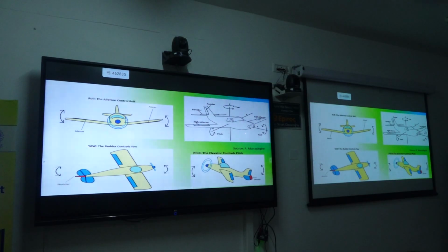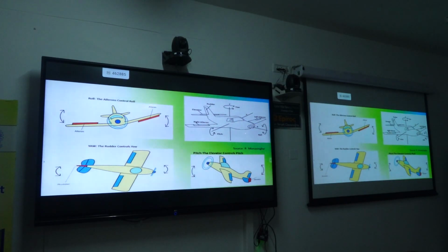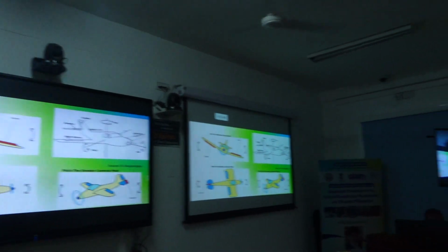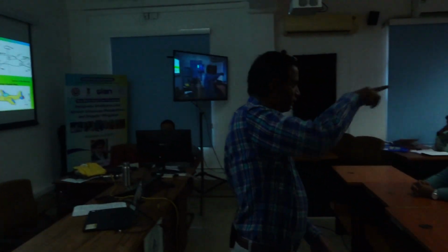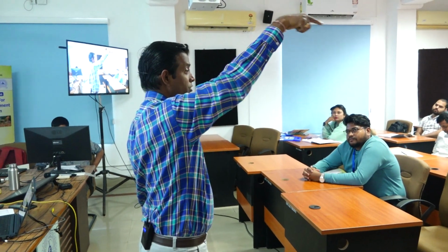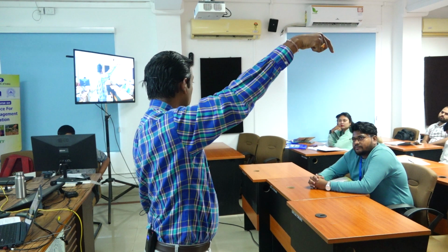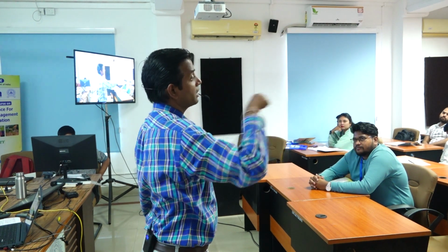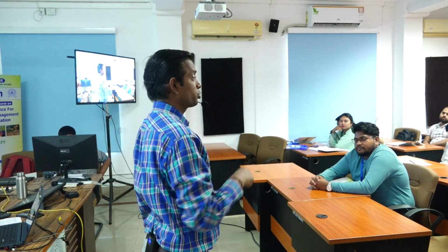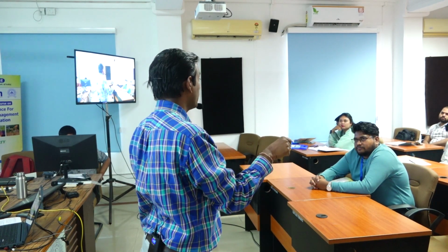That tile will not sit exactly in its place, so the photograph will come like this. Such errors at the time of capture in the atmosphere, we can't do anything about. Now you should identify what the error is in that particular picture at the time of post-processing. Within the limit, we can correct it.